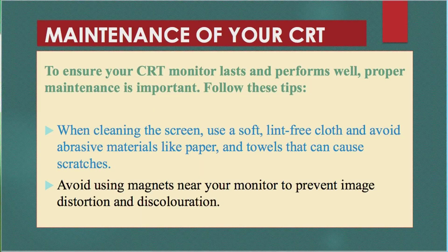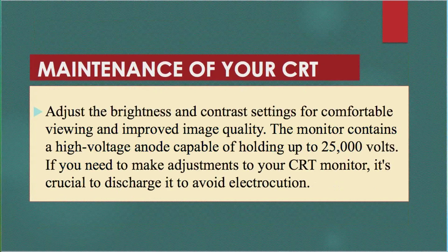Now there are some points to be remembered when maintaining a CRT. When cleaning the screen, you have to use a soft lint-free cloth, and you have to avoid abrasive materials like paper towels, because they can cause scratches on the monitor. Next point, you have to avoid using magnets near your monitor to prevent image distortion and discolorization. Next, adjust the brightness and contrast settings for comfortable viewing and improved image quality.